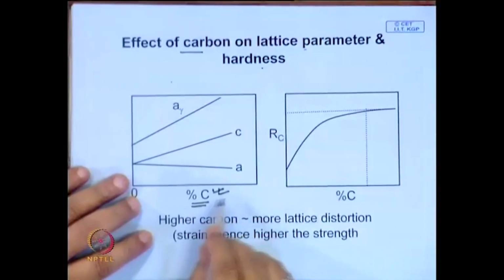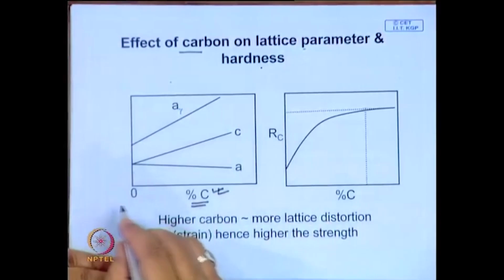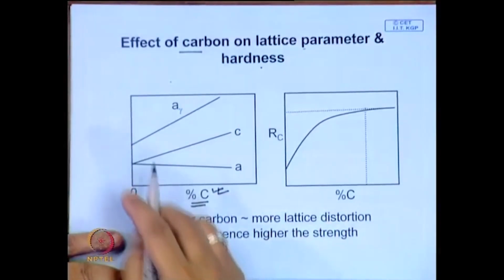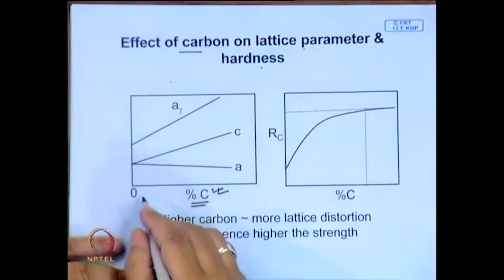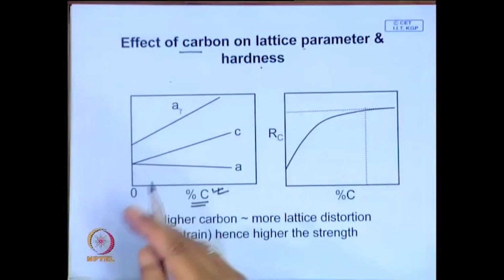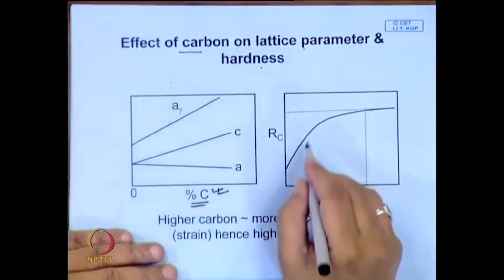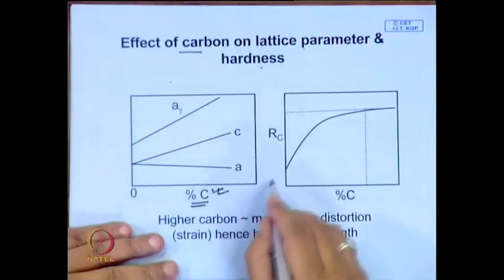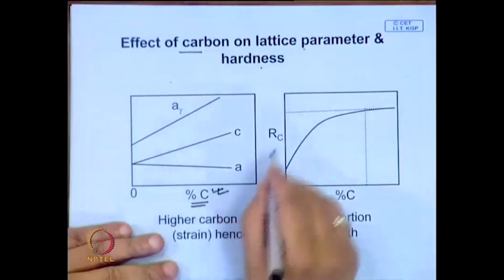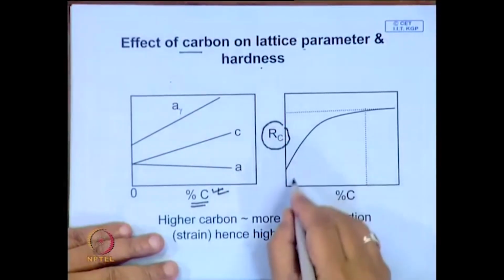You can see it only under a transmission electron microscope, and the lath or plate interplate spacings are of nanometer dimension, maybe several atomic layers, say 8 to 10 atomic layers. So it is actually a nanostructure. Such a fine structure is definitely associated with increased hardness, which is reflected over here.